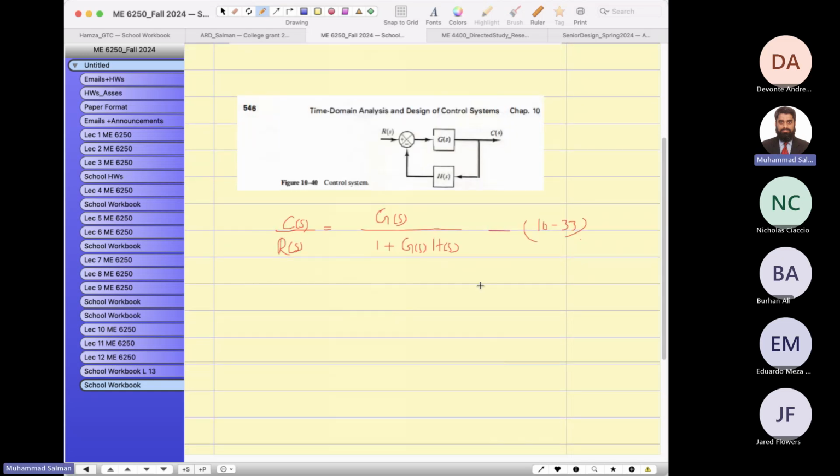So the characteristic equation is this one. Let's assume this is in the Laplace domain rather than writing s every time. We just write down the big letters, and that equation equated to 0 is the equation of the root locus. So the denominator in G: GH equals -1,